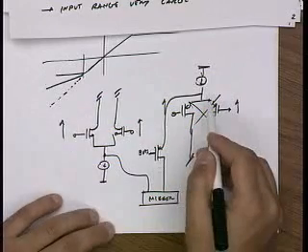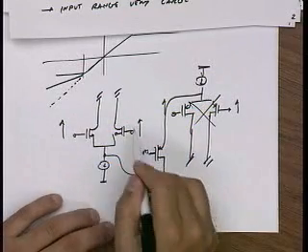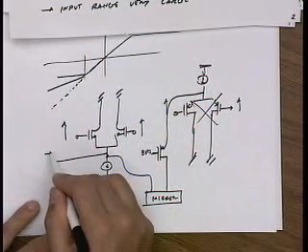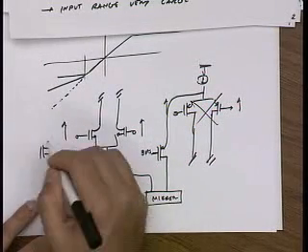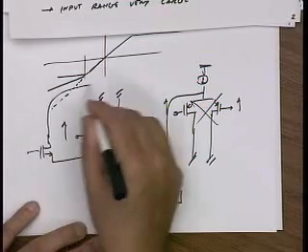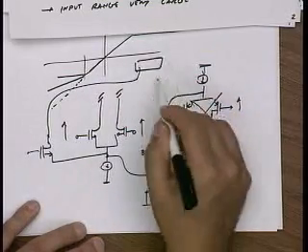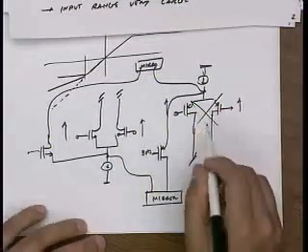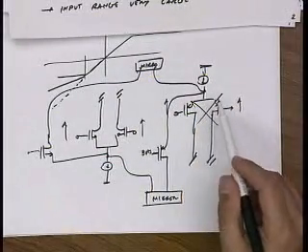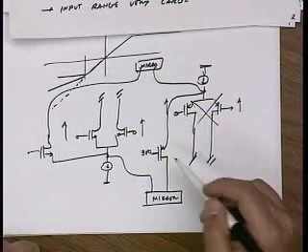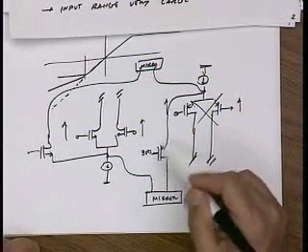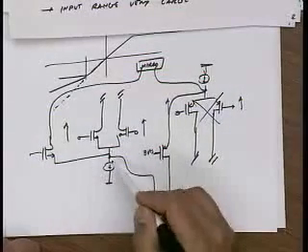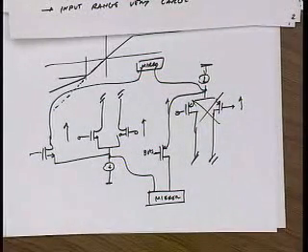And I can do the exact same thing over here. When these guys turn off, I can add another transistor to take this current, mirror it, and add it to here. And so if I design these right, this transistor will only activate when these transistors turn off, and it'll take this current, add it over here, so we get higher GM.